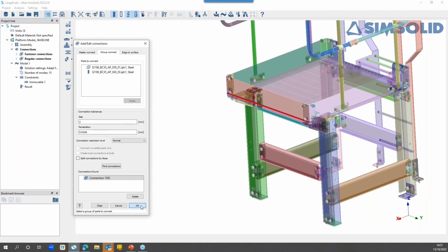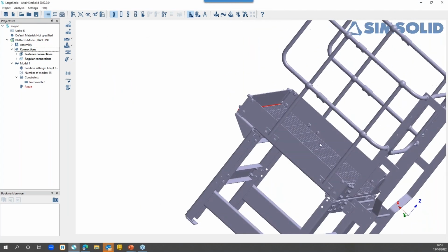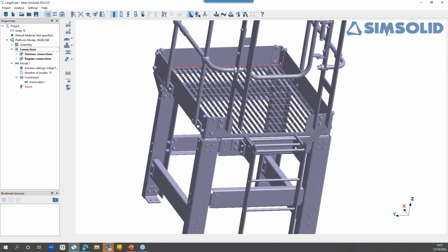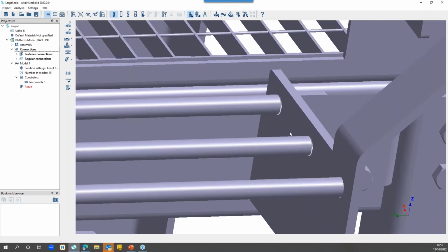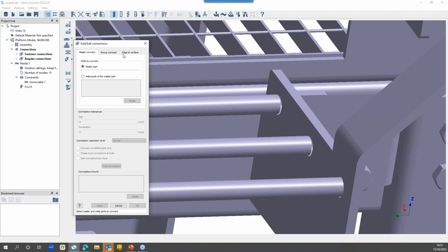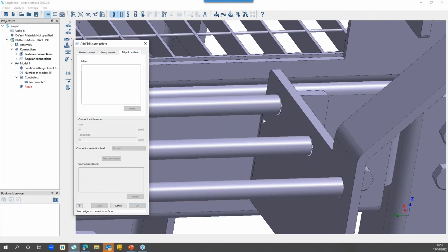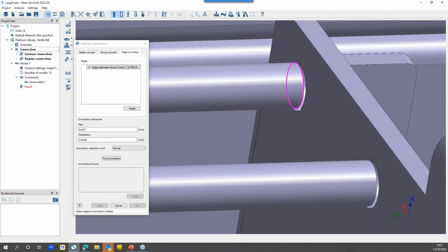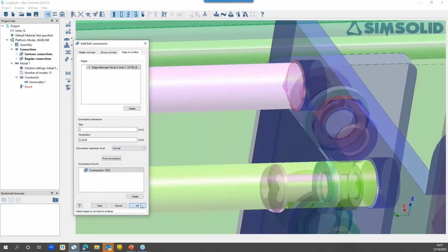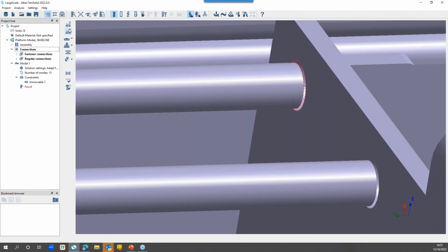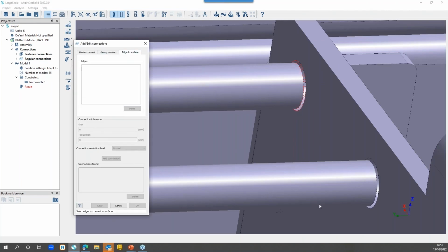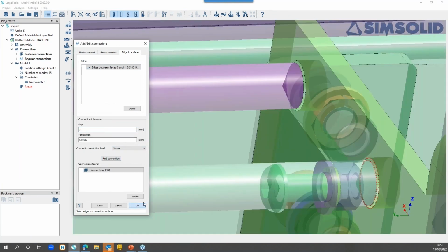It's connected now. So let's go to the other side. The reason why it didn't connect is a gap between it. This one's fine, it goes through. So let's do the same thing again. I'll use a third option this time to show you what else you can do. Again, make it 2, then find connections, press OK. Oh, I forgot to do that one, so let's do that one again. This one and this one, make it 2 again, find connections, and I'm happy with that one.